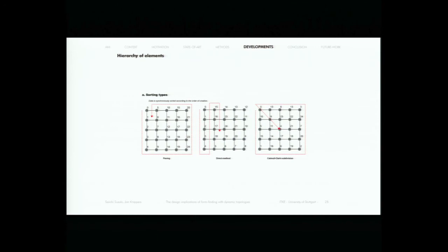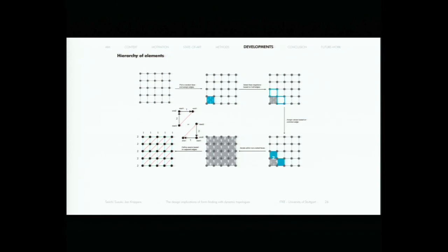The problem here is that since we have different meshing algorithms, data is sorted in different ways, leading to unsuitable combinations for applying the surface element. To face this problem, we design an automatic process of edge categorization, always leading to suitable triangulations for implementing the triangular element. The process is iterative: it starts categorizing edges and sorts data in such a way that all the diagonals of the quad faces are aligned and oriented in the same direction, which is required to create the seams for the constant strain triangle.